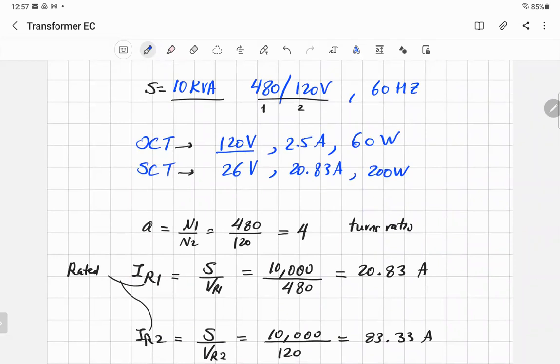Not like open circuit. Why? Because we always start from 0 and increase it gradually. We never go to the rated voltage. We try to get close to the rated amp. So to know where the measuring instrument is, you look for the amps in the short circuit test.